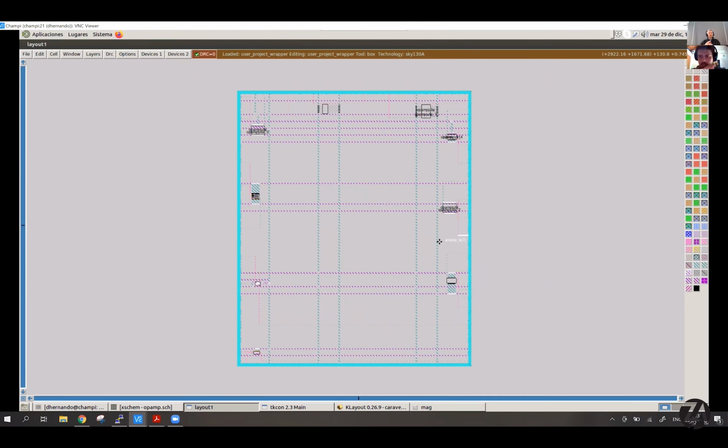Okay. They don't need configuration from the Pico microprocessor, but in the case of the ring oscillator and the PLL, I have to enable the outputs because they are digital, and for the PLL, I have to enable the clock so it can run.